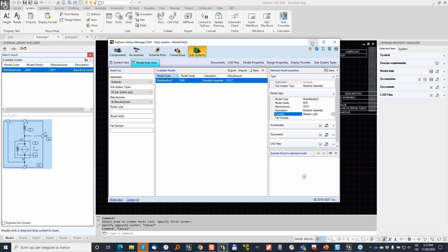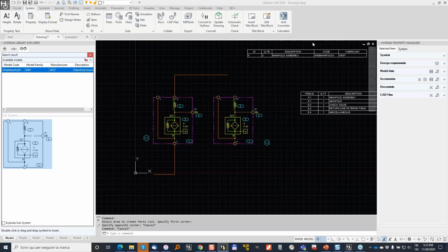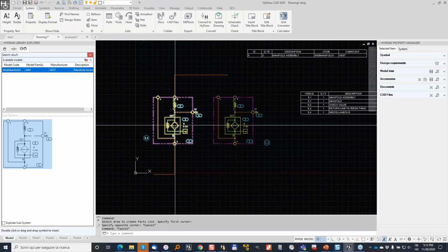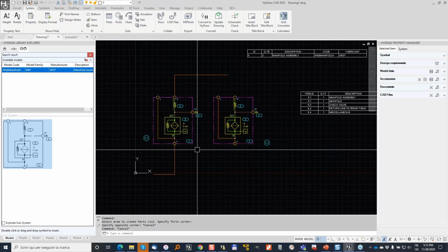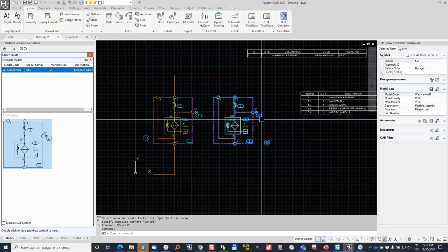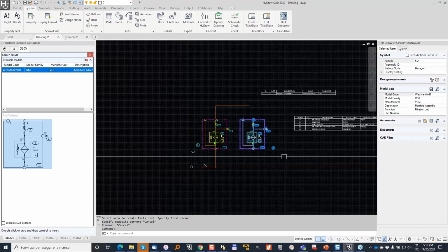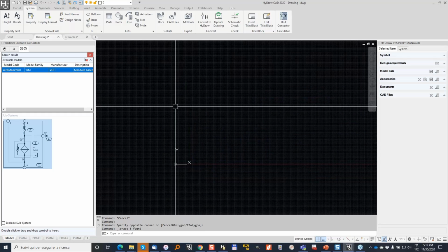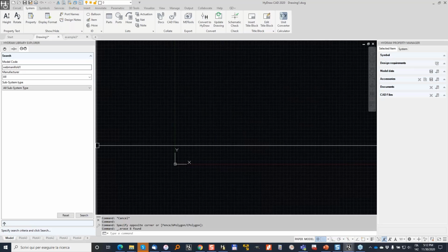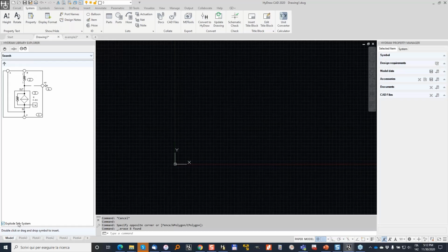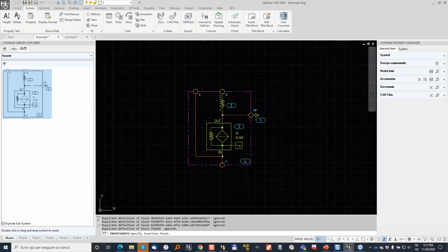Another usage for the subsystem is frequently used application circuits you want to start with. So in this case, it means you are not going to use this as a complete symbol, as a group of symbols, but you want to use them as loose items to maybe start to make a new diagram. So in this case, we will use the insertion of the subsystem in exploded mode. So in exploded mode, you place a symbol and the subsystem will be placed as loose items.